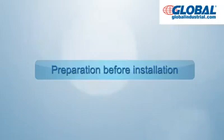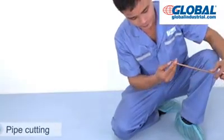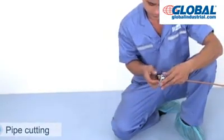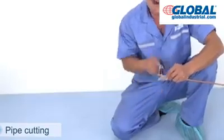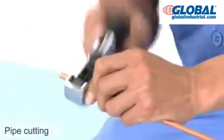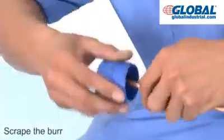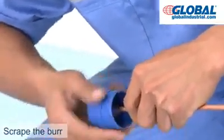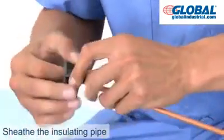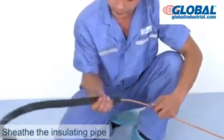Preparation before installation. Pipe cutting. Cutting a suitable length of copper pipe is required. Turn the pipe cutter slowly and keep increasing force gradually. Make sure there is no deformation. The cut surface should be level. Remove the burr on the side of the copper pipe with a scraper. Use rubberized fabric to wrap the copper pipe head to prevent foreign materials from entering. Sheathe the insulating pipe.